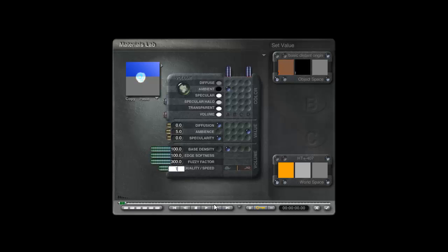If you set the quality right down, it becomes quite crude, and whichever way you look at it, it looks like a cylinder, because you're relying on the additive effect to show you what it looks like, and it's made up of so many slices. As you increase the quality to very high levels, it will slow the render time down, but it'll fill in that sphere. So the rendering of it, which is done in concentric circles, will match the shape inside, and that gives you your different effects.